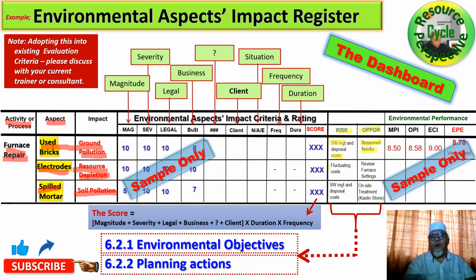Okay, and also we've got problems here with the electrodes. The cost of electrodes is a yo-yo stuff, depending on the country, oil prices, etc. And what we can do, from my discussion with these people, is all about setting, operational setting for the furnace with the correct setting, and of course with the correct type of electrode. There are varieties of electrodes. We've got to use a state-of-the-art, good quality electrode, and it lasts 2 or 3 times longer than some OEM stuff and costs just about 150% more. It's worth it. So we got to look into all this cost saving, okay?